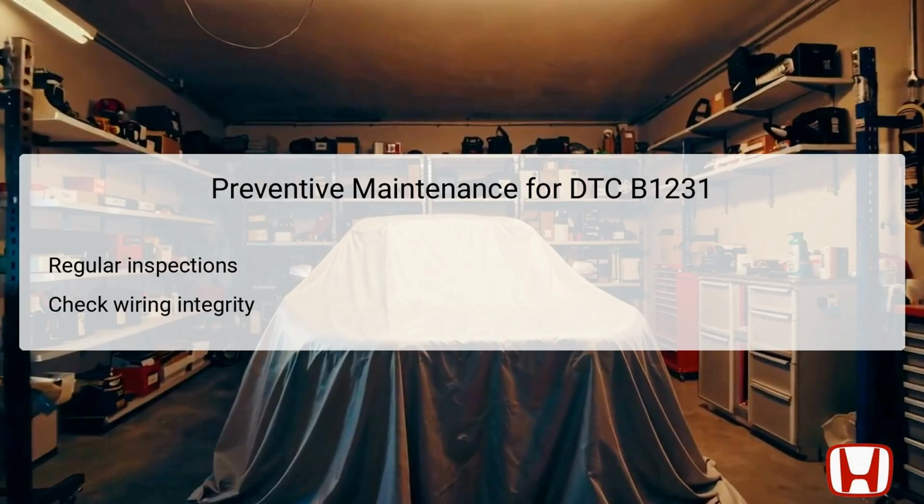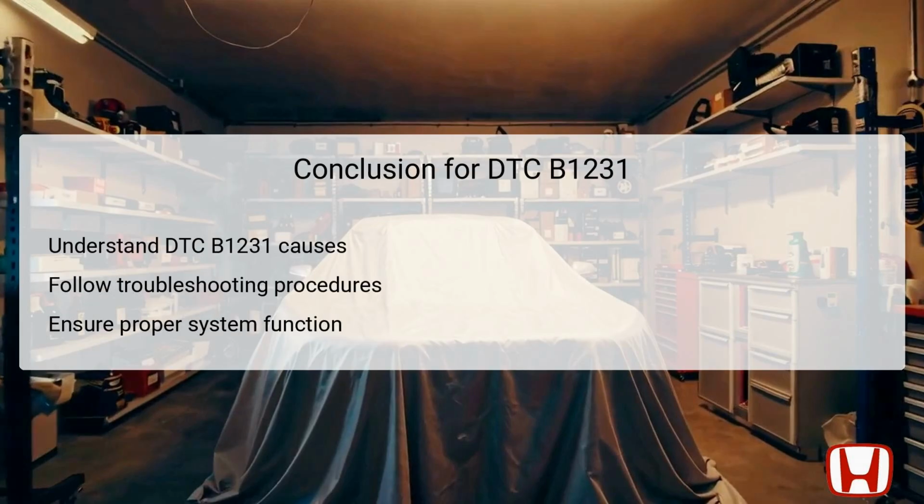faults. Staying ahead of potential concerns can greatly enhance the longevity and reliability of the vehicle's climate control system, ensuring consistent performance throughout its lifespan. In conclusion, understanding DTC B1231 and its implications for the Honda Accord's climate control is crucial for maintaining optimal comfort for occupants. Identifying the causes of the fault, such as issues with the evaporator temperature sensor, wiring, or the climate control unit itself, is essential for effective troubleshooting.